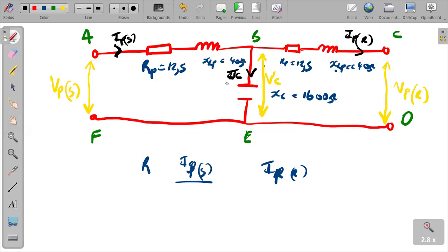And that's the T, right? Remember, we said this is a greater value. This one is greater than this one always, due to the losses that have occurred in between, due to the resistances and the inductances in the transmission line, right? So let's now perform calculations. What are we looking for? We are looking for the sending end current, which is this one.